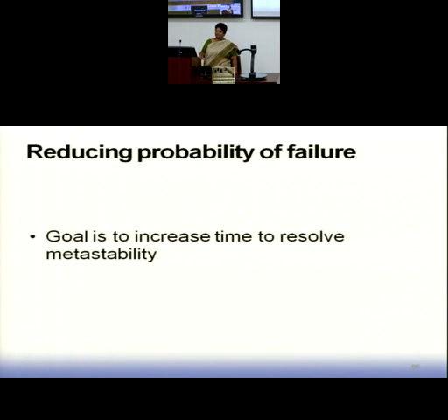So now, I want to increase this MTBF or decrease this probability of failure. Something which is in my hand, apart from VIH, VIL, which has only limited impact, is the waiting time. Again, it's not that I am given an infinite amount of waiting time. But you have to somehow design a system which does not go into failure.